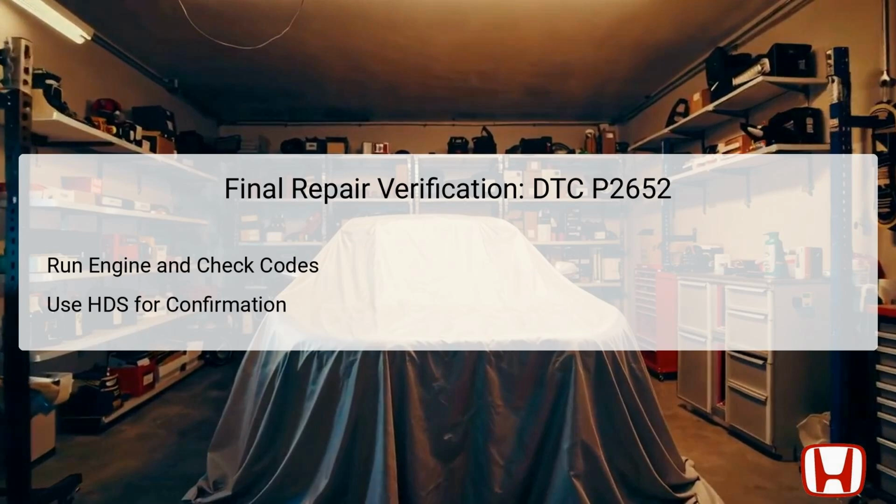After completing the necessary repairs for system components related to DTC P2652, it is crucial to conduct a final verification to ensure the problem has been resolved. Start the engine and let it idle for a while before using Honda's HDS or Honda Diagnostics system to check for DTCs.